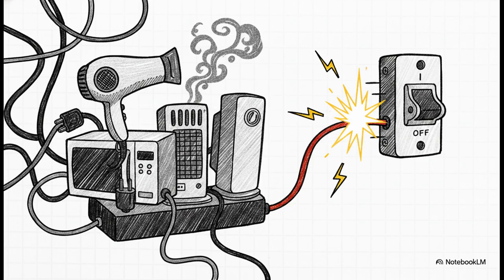And this brilliantly illustrates the flip side, right? The limitations. This system requires significantly more complex wiring than just a simple series loop. Plus, because every added load increases the total current, if you plug too many high-power appliances into one set of parallel outlets, you're going to draw massive amperage. That risk, overloading and overheating the wires, is exactly why we have circuit breakers and fuses. They exist to literally sever the main line and protect the system before a fire can start.